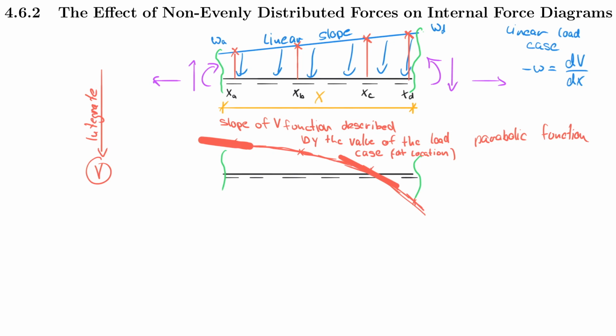So we now are ready to actually indicate our diagram and state that all of this here is really positive shear force, whereas this down here is a negative shear force. And this is just a symbolic representation, because we don't know what's going on here on the left, we don't know what's going on here on the right. We're just stating that due to the linear slope here, we would have a parabolic function that slopes, in this case, downward. And of course, we randomly let it go through 0 here. This could be different depending on what happens here and here.